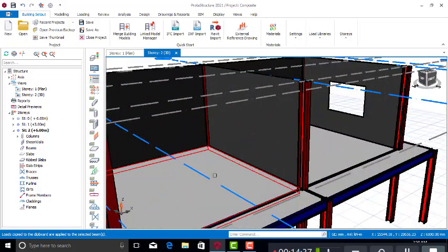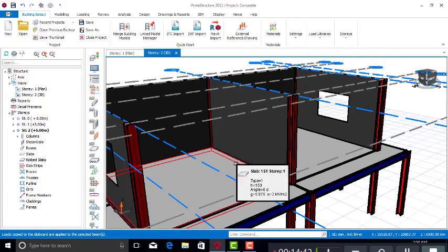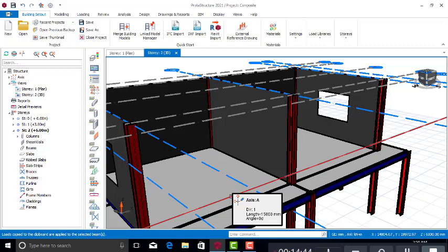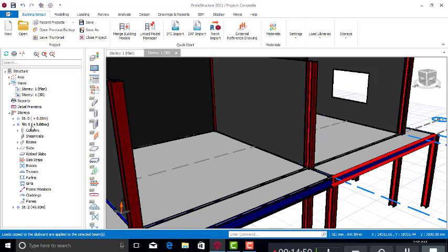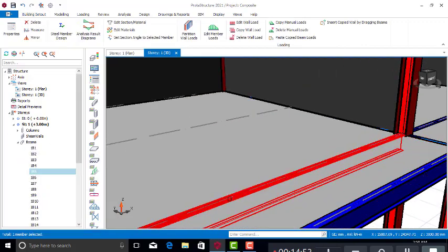Then for the front we are going to have another wall. Then that wall is going to comprise two openings. We have one window and one door. Okay, so that's going to be on this beam, right? So you can do the same thing here. Just make sure you're on story 1. Then let me click on this beam. You can click on the beam here.